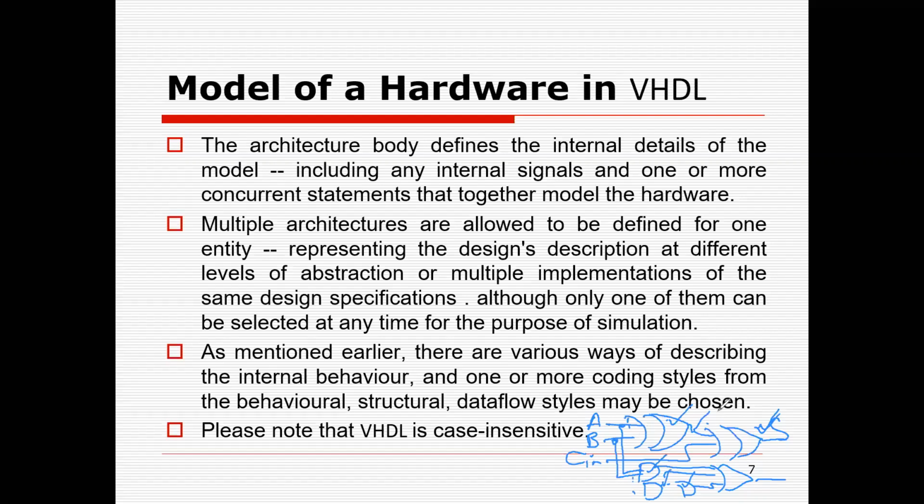Okay, so everything is kind of being executed concurrently. So that is the difference between a C language and a hardware description language. So I need concurrent statements in hardware description language which can define my structure. We will talk more about concurrent and sequential statements later. We also need sequential statements when we are describing the behavior.